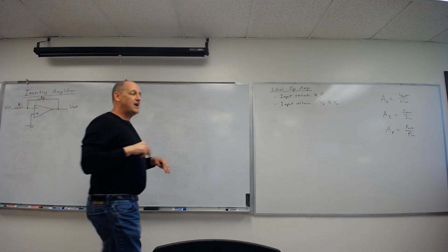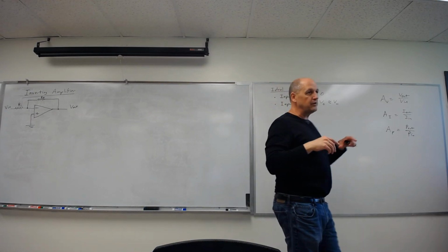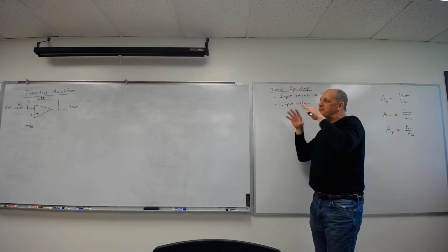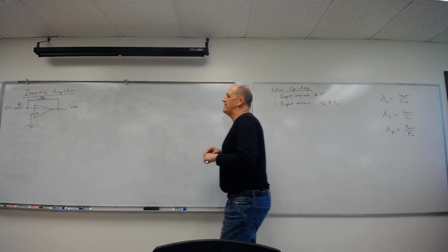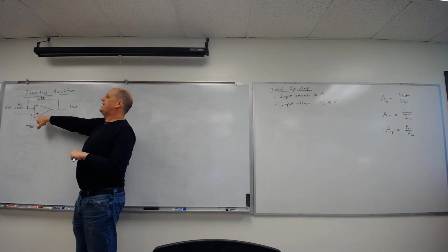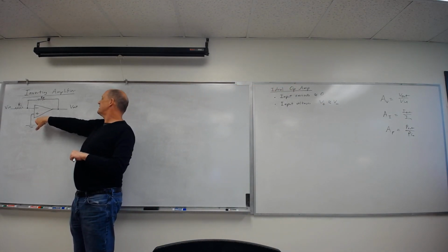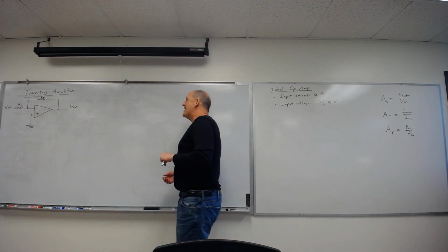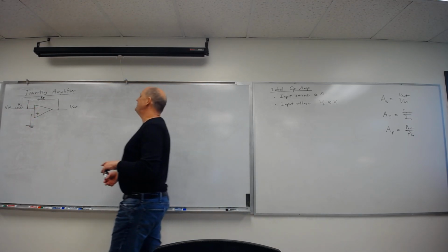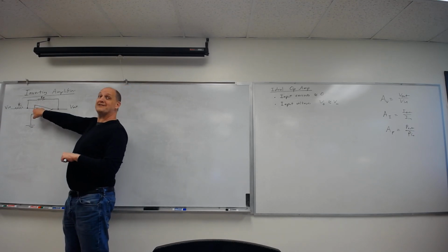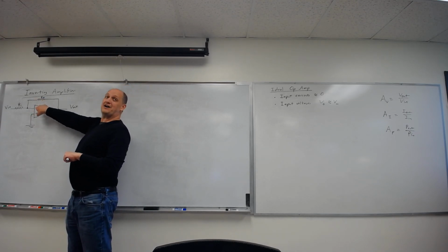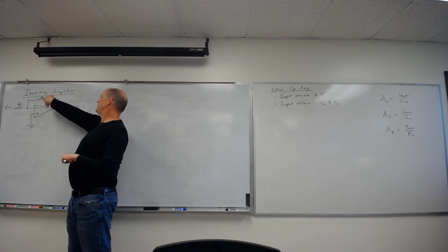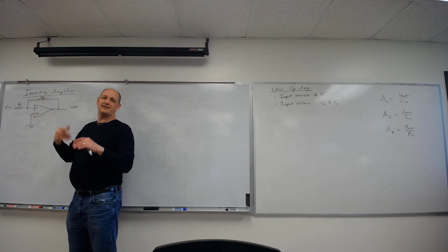This has two big advantages. Number one, I'm no longer strictly depending on this amplifier's internal amplification. In fact, as long as we're talking purely theory, I don't even need to know what it is. It's going to get the same numbers regardless. In reality, the actual amplifier will matter, but it really doesn't matter if this amplifier has a gain of 100,000 or 150,000, because if it has a gain of 150,000, I would get more amplification, but then I would also send more back to the input, so I just drive that back down so it has the same gain.